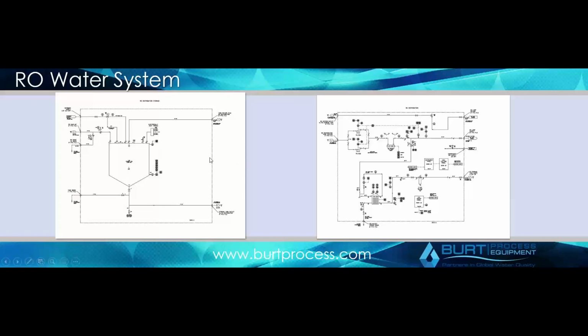And then we move into our storage tank. In this case, we have an RO break tank as well as a DI break tank. So we're going to come into our RO storage tank. These are your vent filters, conical bottom generally, because you don't want to have any kind of water buildup or stagnation in your system. This is your loop return, your spray ball. This is just a drain over here, and then you have your primary suction. This goes into your distribution for your RO water, which goes through UV and then has its own separate loop out. And then this begins to feed your DI process.